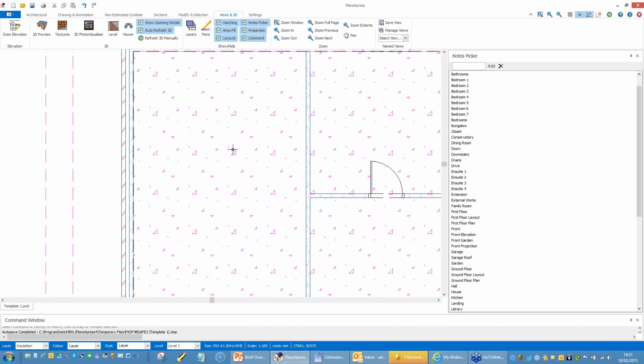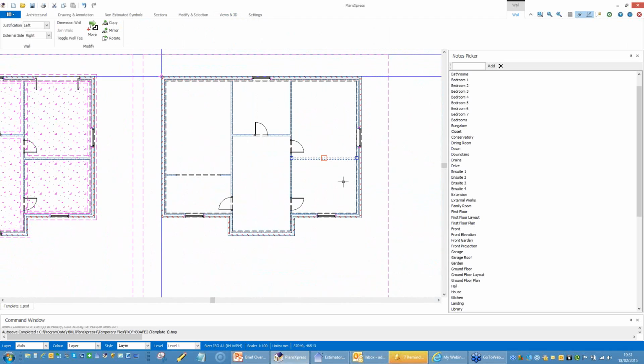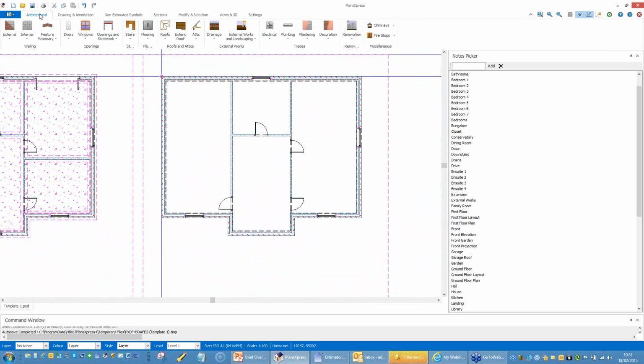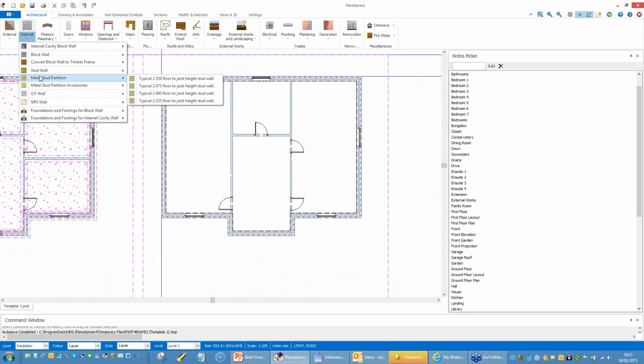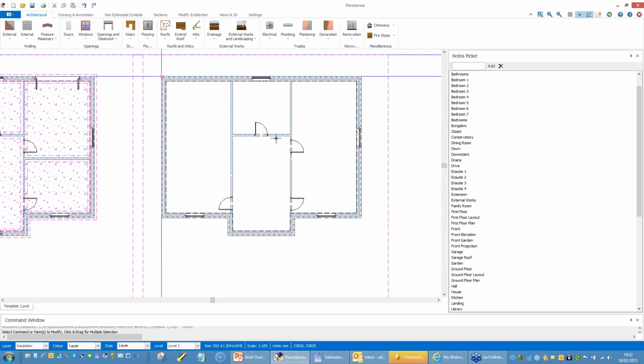And you can see it's copied that floor. Well, clearly I don't want the concrete floor there, so I can delete that. But I've now got a direct copy of upstairs. Now, the chances are the upstairs is actually going to be a slightly different layout. I may well keep this area to form a staircase core. So I'm going to take out those walls, for example, that structural opening and those walls. I could then, of course, go back in and place some stud walls for bathrooms and bedrooms and so on.